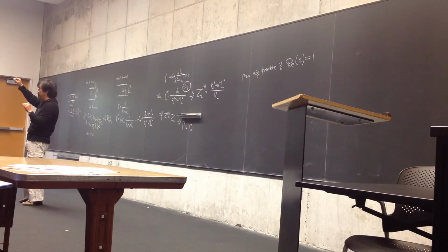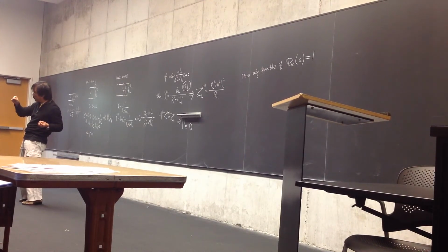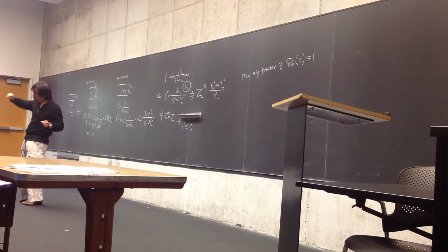And if you want, you can rotate it 180 degrees to find the admittance on the Smith chart. And then along the transmission line, one thing doesn't change: the magnitude of gamma doesn't change. So you take this point and connect it to the center of origin. You are able to draw a circle here, centered at the origin, and here is one point on the circle. So you draw a circle.